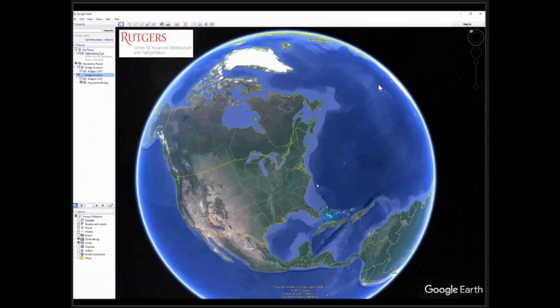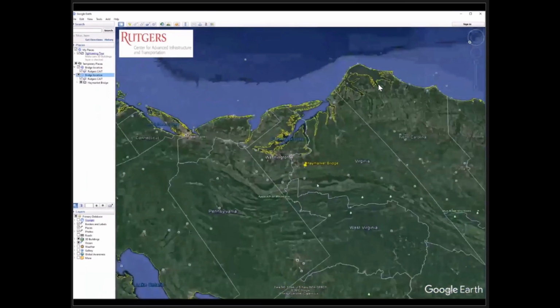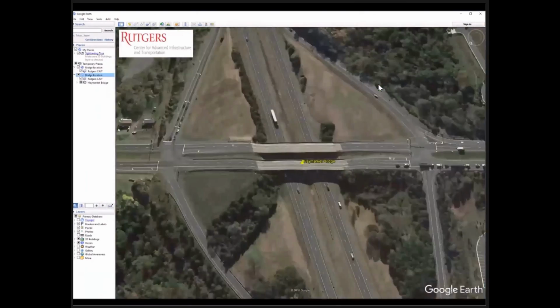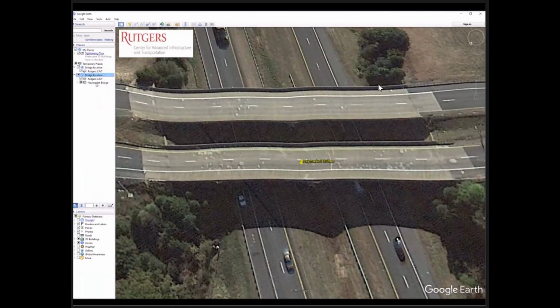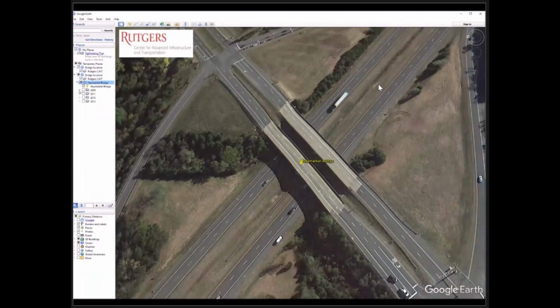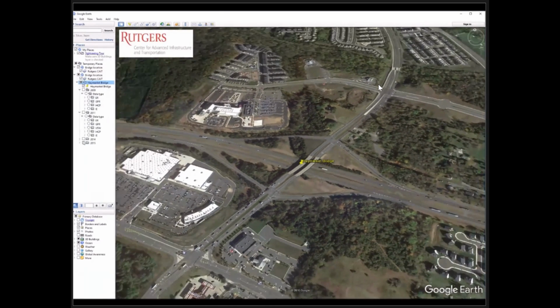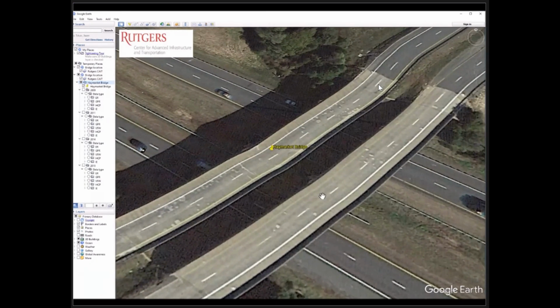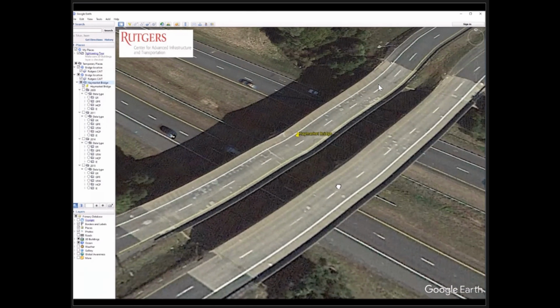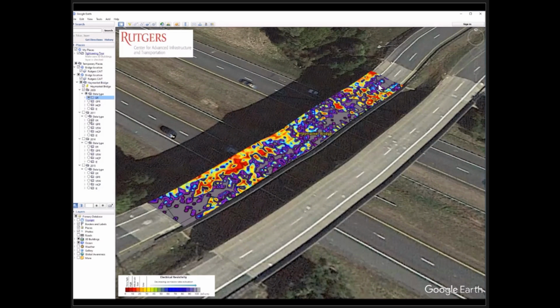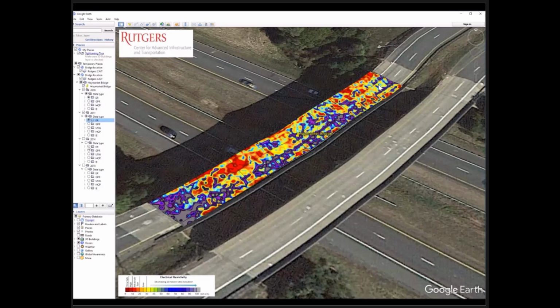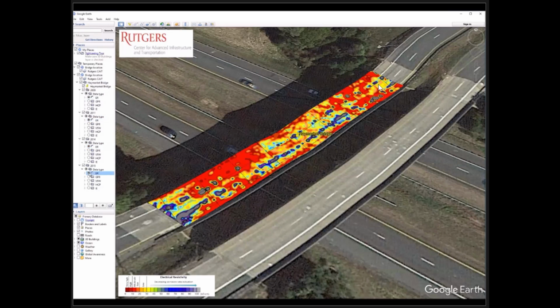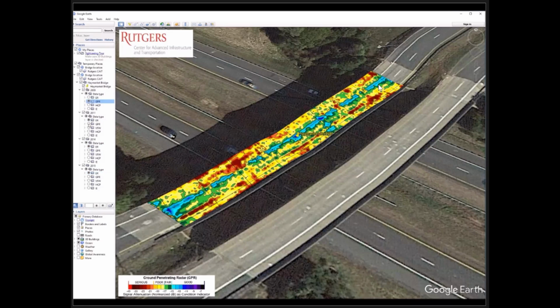Okay, what is also good about these condition maps is that on the network level, if you would like to provide a very intuitive presentation, we have done it in different ways, but probably the most convenient one would be to place those maps in Google Maps. So for every bridge, which has its own coordinates, you can recall those condition maps. Here you can see on the left side all the maps for this bridge, and you may go from one year to another and, in a very intuitive way, recognize the progression of deterioration for any particular structure.